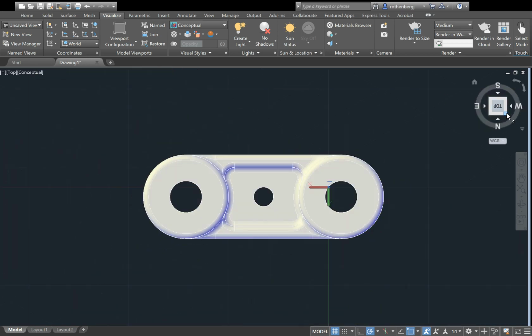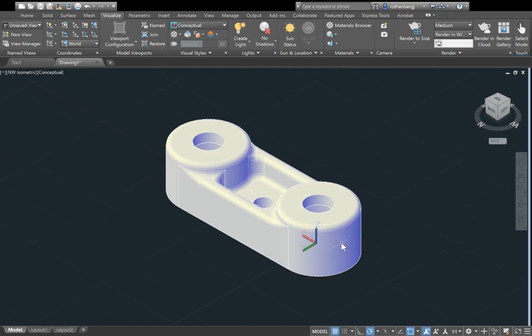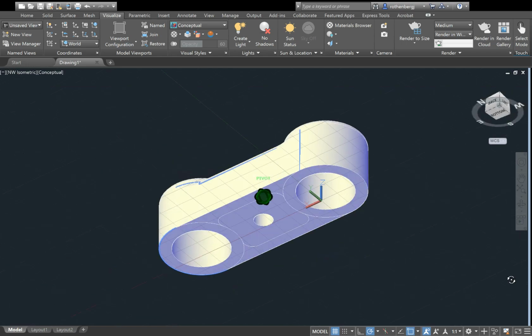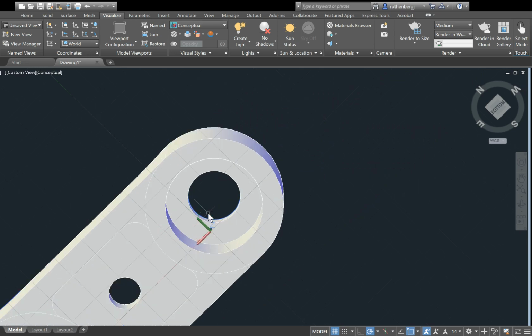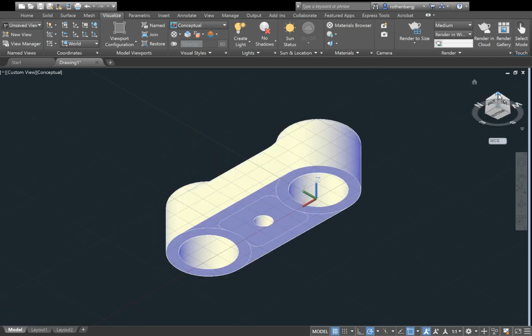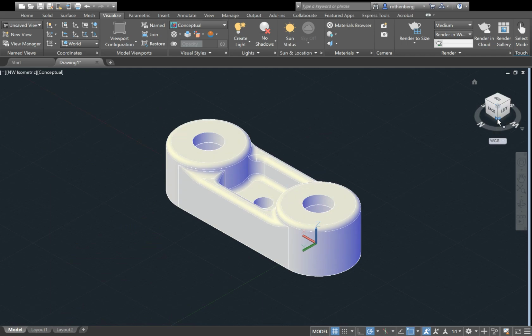So you want to make sure that you do this before you cut the corner off, or else it won't be exactly right. So now we're basically done. We just have to do just 2 more edges. So fillet, hit enter, select the intersection of the 2 cylinders of the cylinder cavity and the physical main body. It should still be set to 1/8, so hit enter again, and it should be done. Do the same thing on the other side, fillet, click, enter for the radius, enter again. Now that's done.